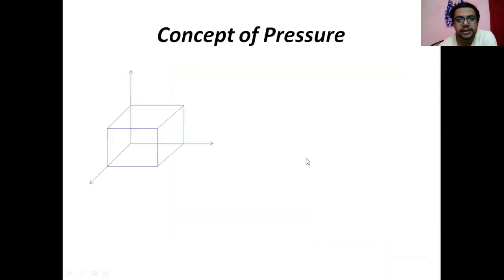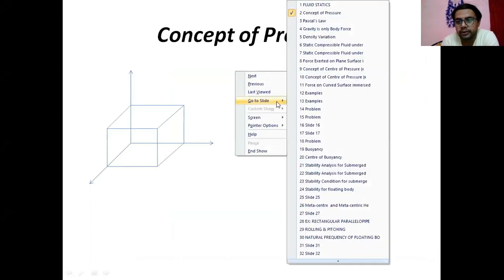So the fluid statics chapter. Previously, the normal component of force we have seen, that is the pressure. What does it mean by the pressure? In macroscopic point of view, the pressure is the time average force per unit area. We know that is the pressure from the macroscopic point of view. So here, the pressure is a combination of the normal stresses, the average of three normal stresses in the opposite direction.